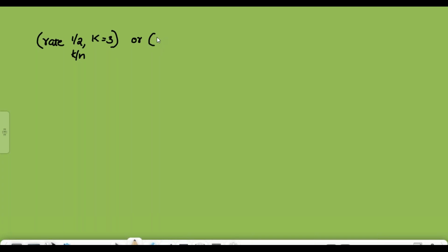It will also be given as you can see in the question paper. Those who have gone through the question paper I have shared, you can see that, or in the textbook it can be seen like this: a 212 convolutional encoder. It will be given like this. Here 2 is the n value, first 2 is n, and 1 represents small letter k, the number of messages, and this 2 is the number of shift register stages, two shift register stages.